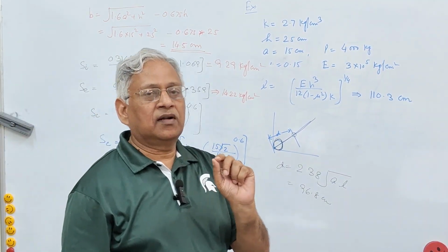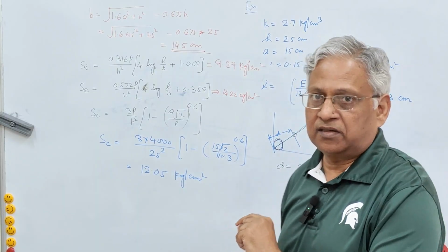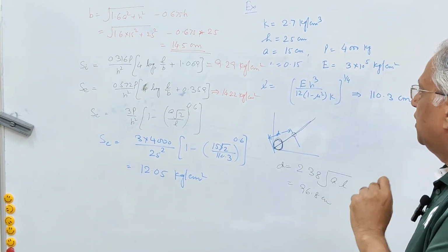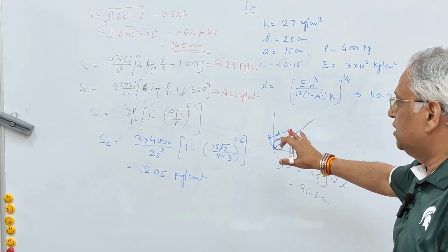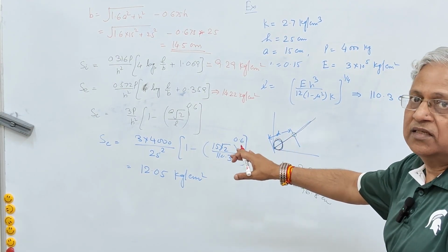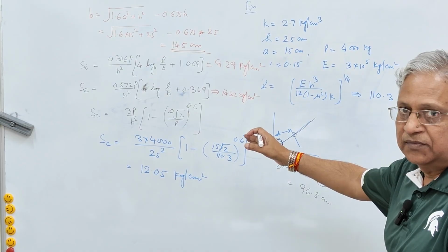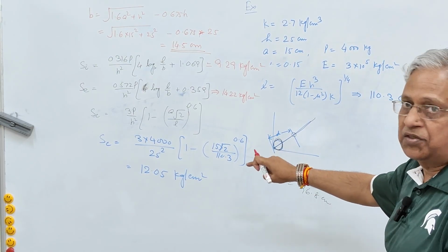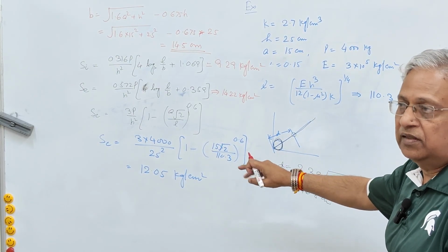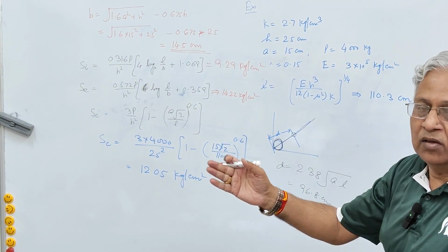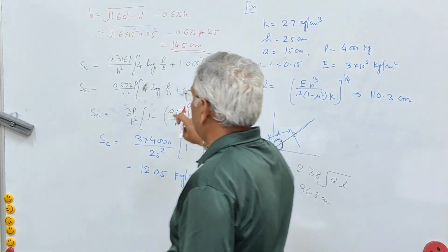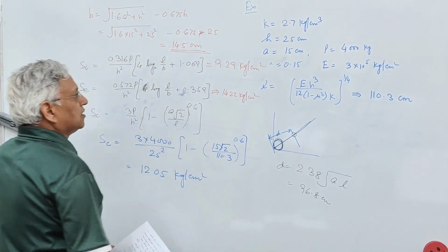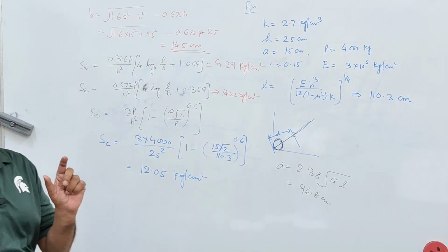When experiments were conducted by subsequent researchers after Westergaard, they found that these equations underestimate the corner stress. Corner stress is higher than the edge stress. And this is the critical position. This becomes very critical position when there is no support provided on the corners. And therefore, these equations were slightly modified to give the results which are close to experimental values.